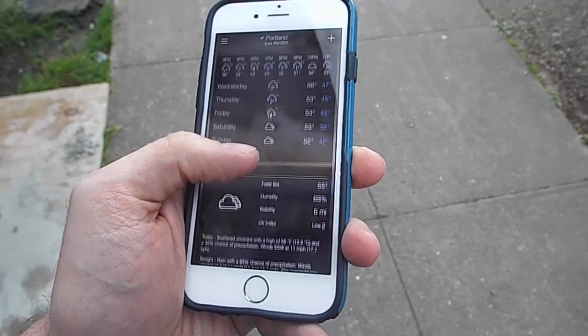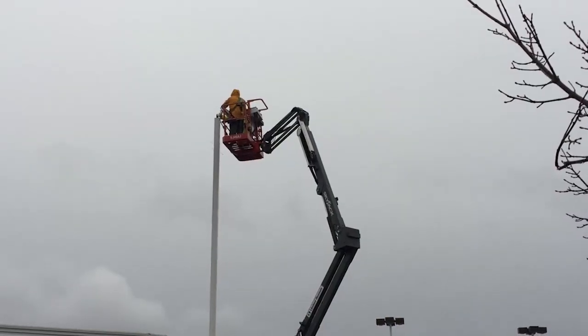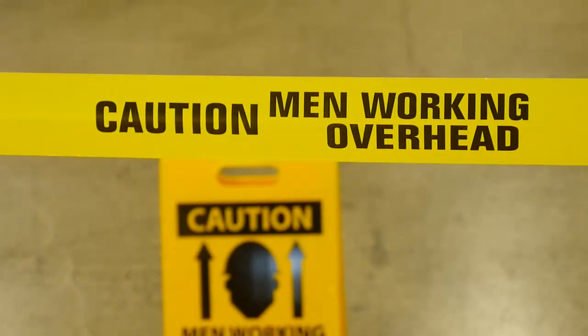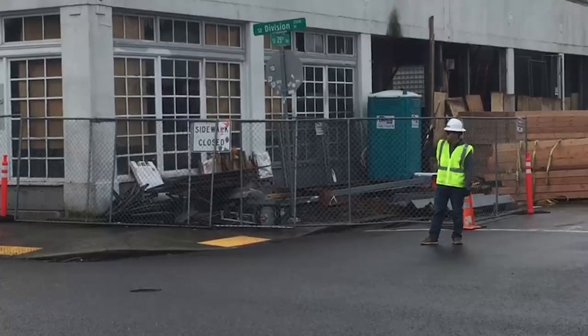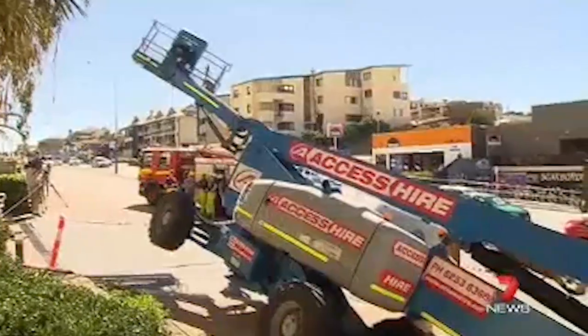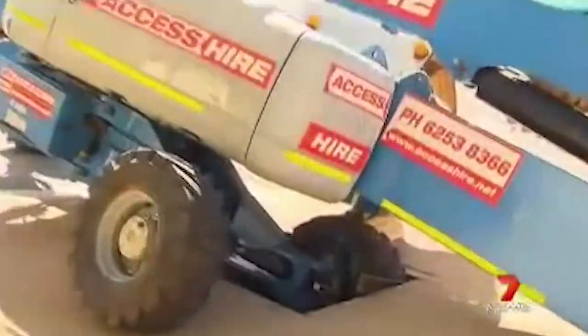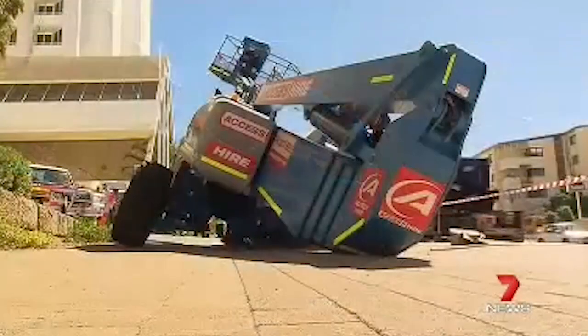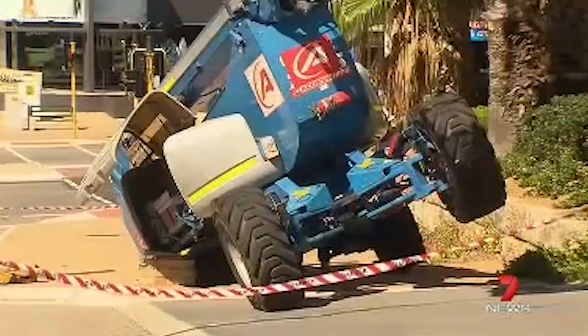Current and forecasted weather conditions must be appropriate for the work being done. Make sure that there are no unauthorized persons in the work area. The work area must be clear of road, worksite, and pedestrian traffic. Make sure that there are no underground chambers beneath the work area. Tunnels, underground utilities, and sewers may cause the ground above to collapse under a heavy load.